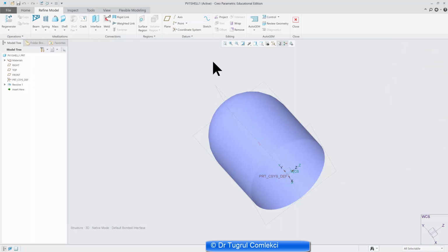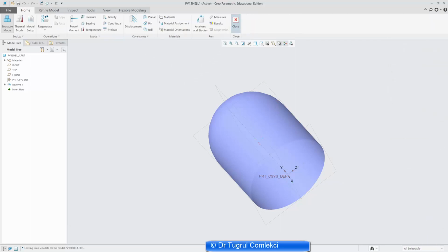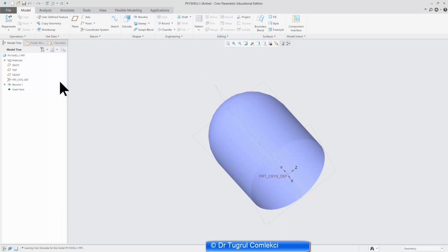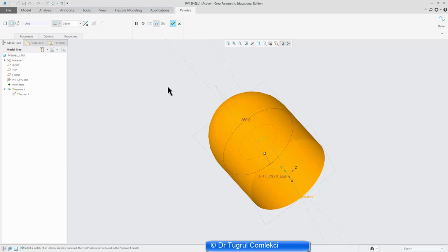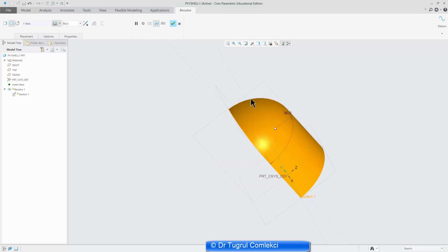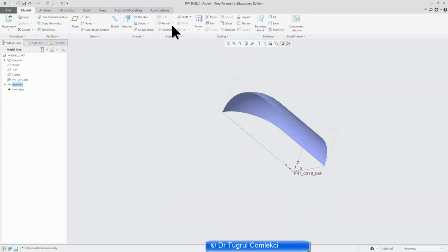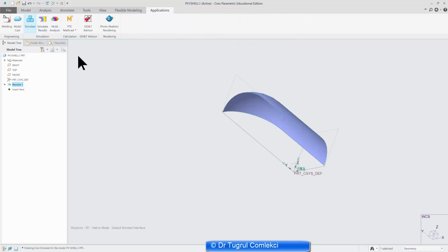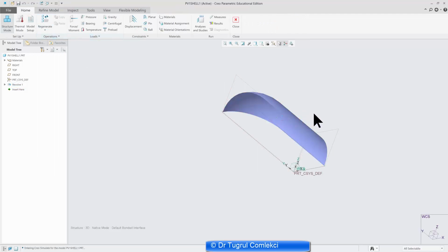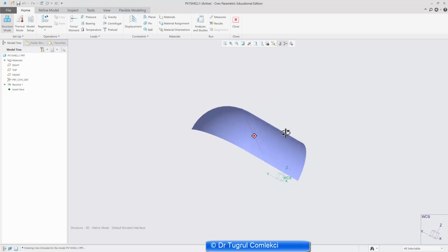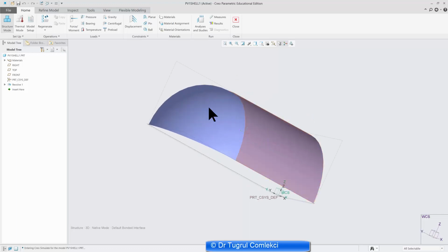So if I cancel that and close Creo Simulate, if I go back to my Revolve operation, I can edit that so that it's only revolving 90 degrees. So if I OK that, and that's my 90-degree revolution of this shell, press OK, and now I can go back to my Creo Simulate and identify my displacement and other pressure boundary conditions, etc.